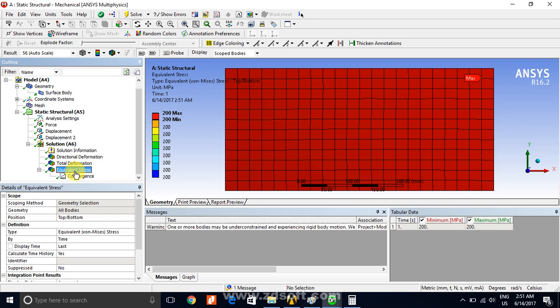So first thing, we have modeled it correctly. Second thing, we have avoided the effects of boundary conditions, which is told by Saint-Venant. Saint-Venant said, if you grip anybody and apply the force at the boundary, there would be boundary effects. So in the simulation we have modeled it very cleverly so that the boundary condition effects are avoided and we get this stress in all the body, and that is how it should be.